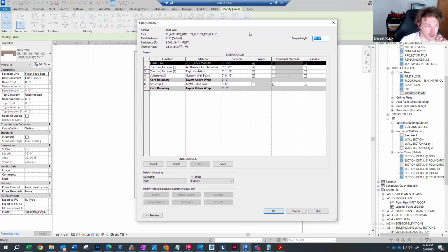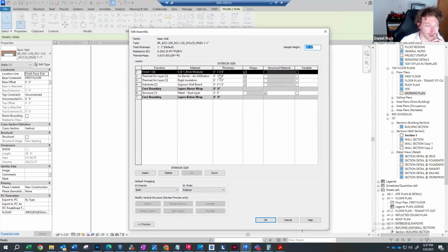In our office, because you're supposed to model things as their actual size, brick as a modular coursing is actually 3 5/8, not 4 inches. We try to model the airspace so that the total thickness of the wall is a full value and not a fraction. So that's why we're seeing this 1 3/8 here rather than like a 1 inch or 1.5 inches.